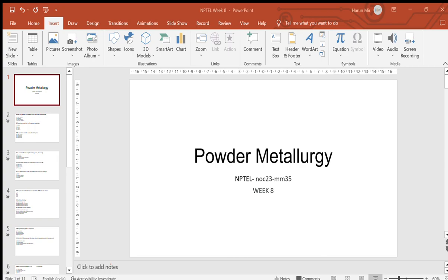In the injection system, it is better to have this homogenized slurry, because you are trying to mix the binder and the powder. So in the injection system, if you have a homogenized slurry already, then you can inject it into the mold and you can expect a uniform distribution of your particles for the compaction. So the right answer is injection system.